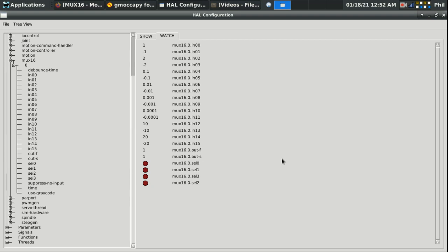So it does tend to get a little confusing when you get that many multiplexers going together. But again, the benefit of it is that we have 16 selections that we can choose from, utilizing 4 wires to our breakout board, only utilizing 4 inputs. So we have 16 options with just 4 inputs being set to true or false. This is a good way to have multiple assignments and utilize a minimum number of inputs to your board, because believe me, you can run out very quickly.